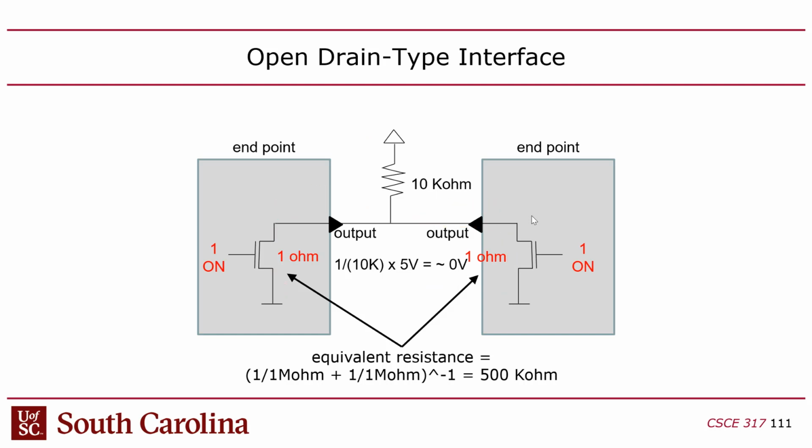Now, what you might say is, what is the advantage then of this? Well, the main advantage is that it's fairly safe, because even if both devices on this shared wire pull down, you may get about double the leakage current, but it's still being shunted through this 10 kilo ohm pull-up resistor. So it's not devastatingly bad if both devices try to talk at the same time.